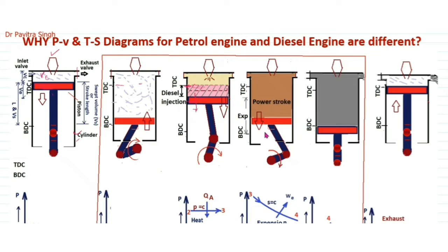You can see in this next figure. So actually this movement of the piston from here to here was the power stroke or expansion stroke. At the end of this stroke, this piston will be here, and this volume will be the swept volume. So this will be the expansion stroke or power stroke. Again this piston will move from here to here, you can see in this figure. So this piston is at the BDC condition at the end of this power stroke.